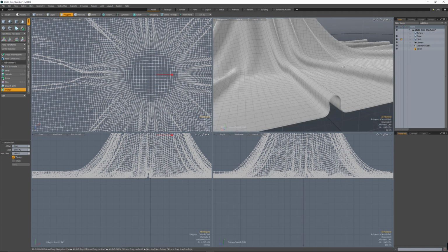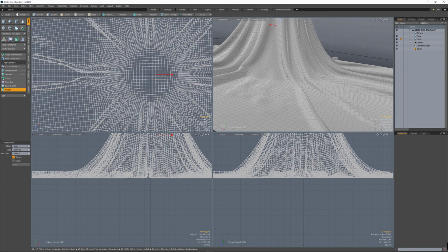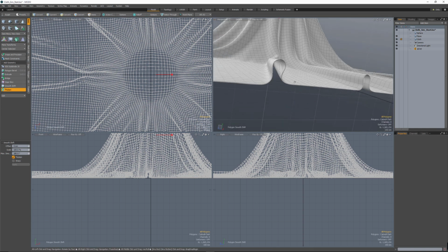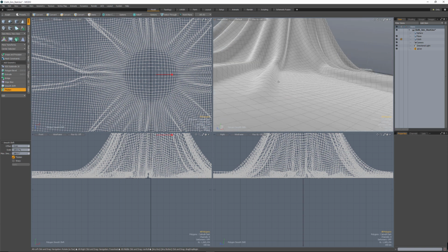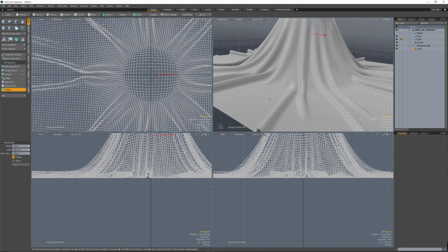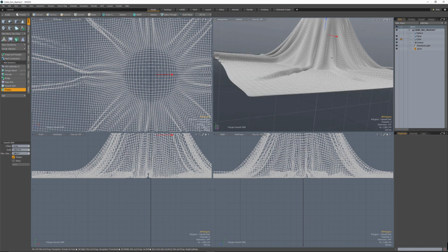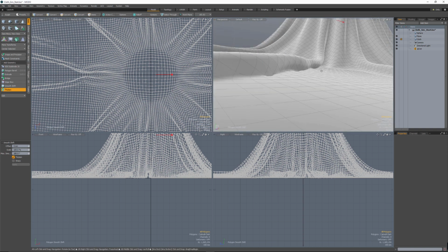And I need to just take a quick tour around while the thicken tool is still active, and I want to make sure that I didn't cause any additional overlapping. If you do see overlapping, you want to increase your max smoothing. My max smoothing is set to 180 degrees, so I'm not really going to have too much in the way of overlaps. If you're set to the default, which I believe is like 44 degrees or something like that, you may have a little bit of overlap.